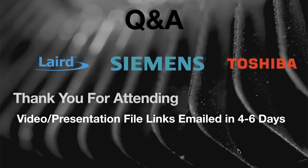Question from Jurgis. Does your DMOS have an automotive version, automotive qual? Can you repeat, please? I don't see it in the written questions. Which one? Your DMOS automotive qual, does it have an automotive qual version? So we have automotive qualification for low voltage FETs, so up to 100 volt. And for high voltage MOSFETs, unfortunately, at this moment, we do not have automotive grade. So again, low voltage FETs, we do have.